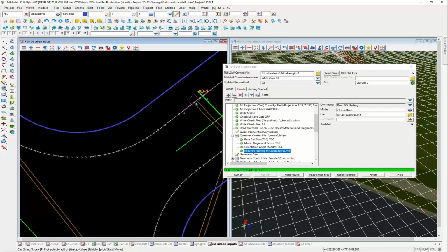I think when we're talking about the improved depth, because the storage in that area is much more accurately represented, having the extra subgrid sampling, especially at the lower depths, you're going to get a finer resolution in the change in depth at those areas. So, Chris, did you want to jump in on that one? I see that as being the big benefit of the subgrid sampling for the depths at SAGs. Did you have any other comments? Not really. I agree with you wholeheartedly there. There's not much more I would add to that, to be honest.